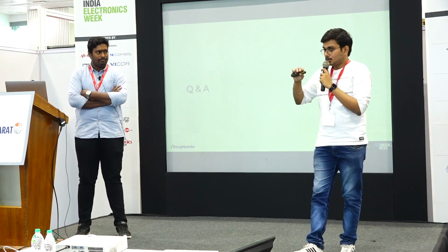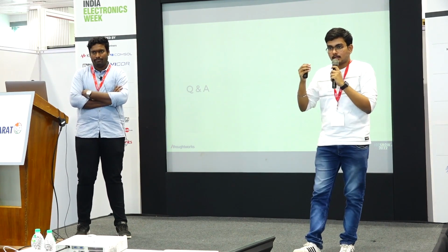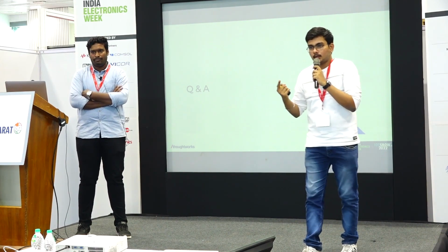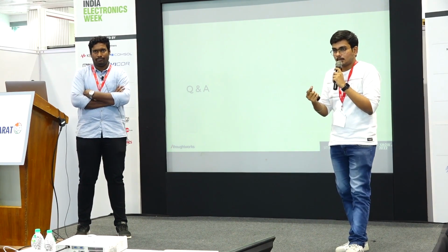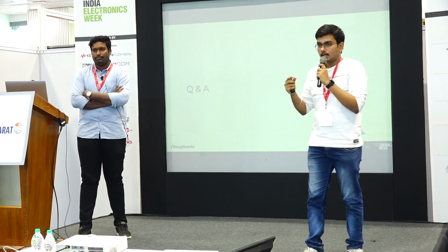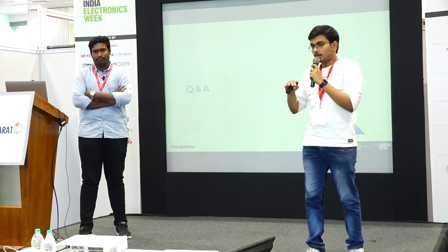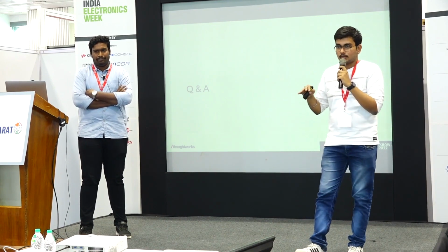How are you transferring this video streaming from the edge, the robot, to the central station? Currently we are doing communication on the local network only. We are using a separate router instead of the corporate Wi-Fi. We solved it that way, because only with the 5 gigahertz Wi-Fi band can we transmit heavy data. But when we go away from the router, it drops some data because of the heavy load. So we incorporated a separate router without internet, and we had a local network for communication.